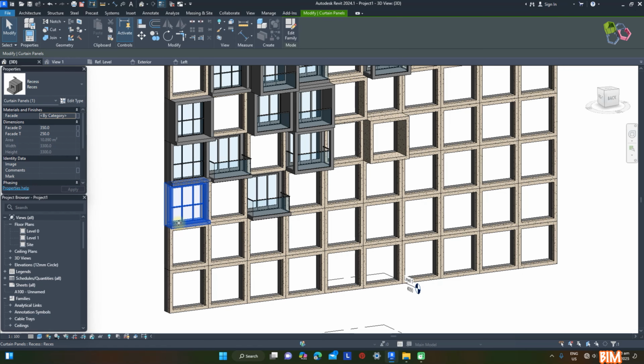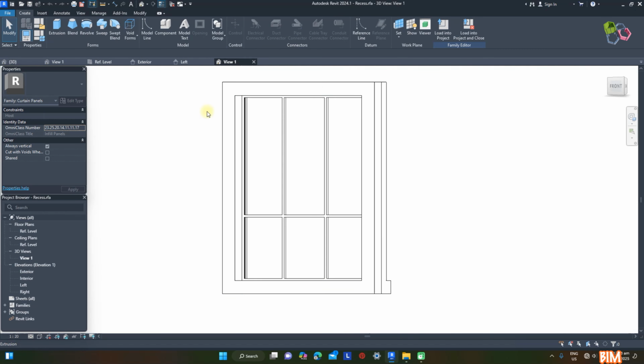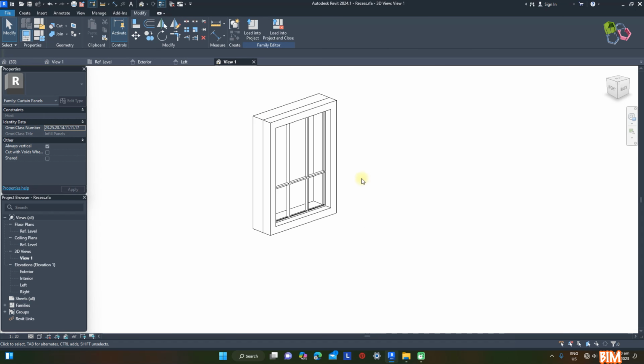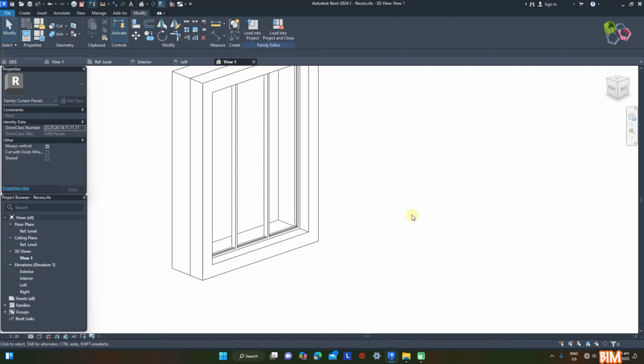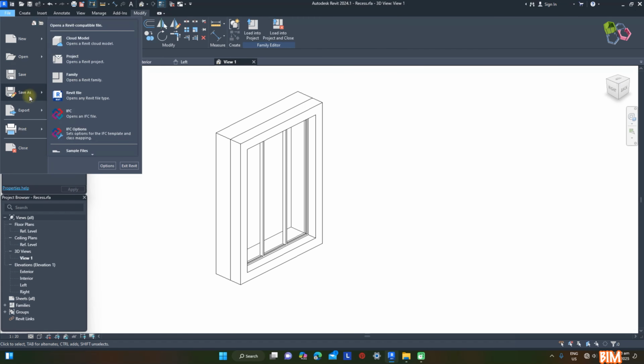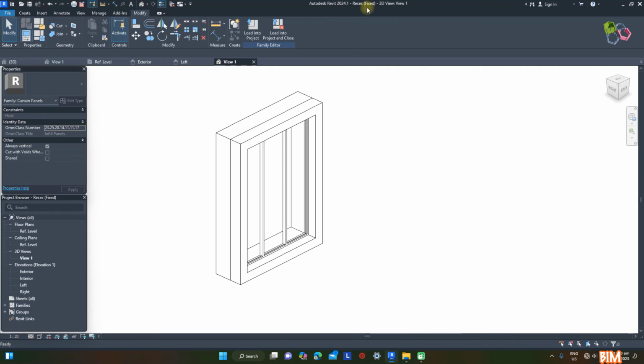Not only these, I also create an additional new fixed glass recess family type to install. Referencing the recess family, I create the new recess fixed family by just removing the sill and horizontal rail. Then load and install.